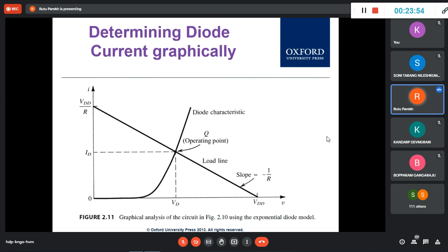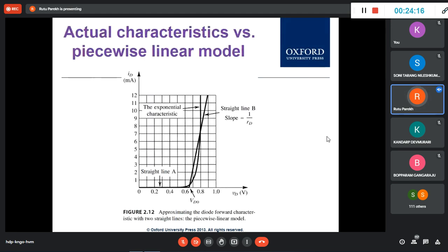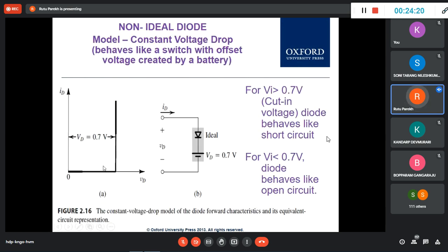That the current will start flowing immediately. It is 0 volt, and if you cross 0 volt a little, 0.001 volt, 0.1 volt, it will start conducting. And in a non-ideal diode, it will conduct at 0.7 volt. So it is just this model that we used. In reality, nothing is ideal. Look, so this was the second level of approximation.